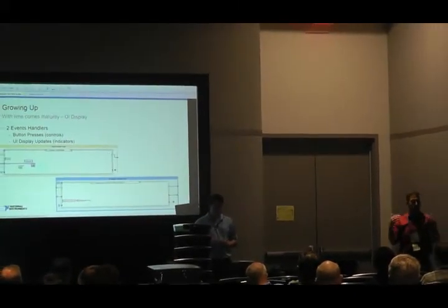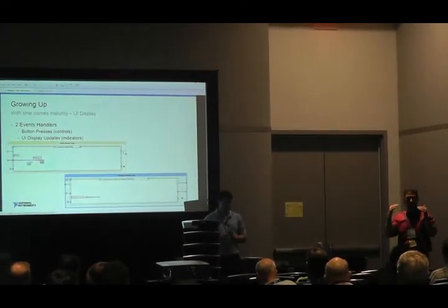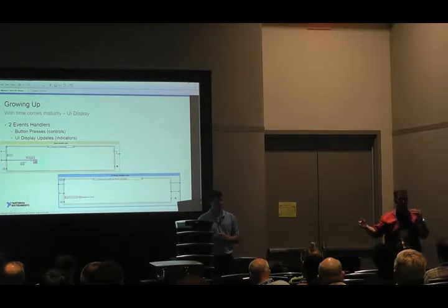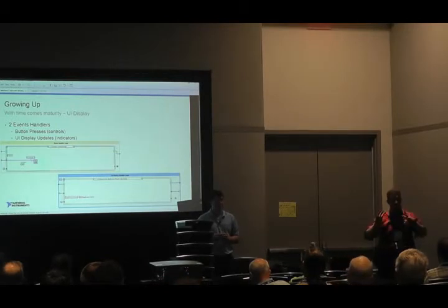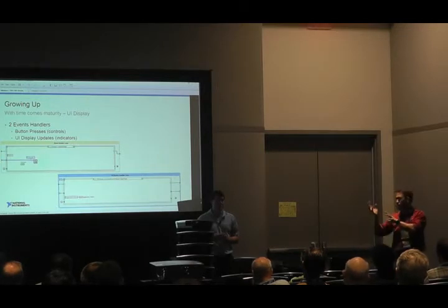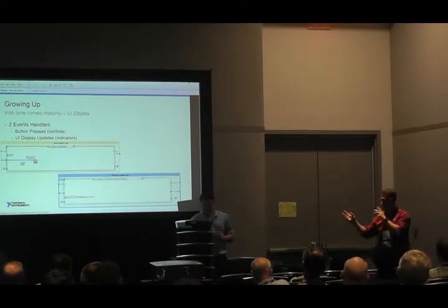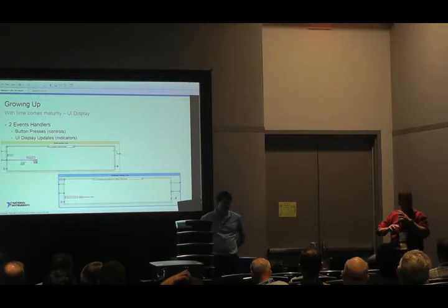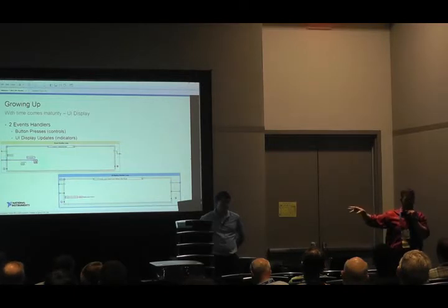However, one of the challenges with that is that every individual time you did update one of those things that needed to get populated in the front panel, you needed to re-enqueue the action of explicitly updating the front panel, update the display. So this was an attempt to not only allow for that updating of the display to happen outside, so that you didn't have to kick the update display dog every so often, but then also it allowed for other event-based things, like status, to happen in the front panel itself.